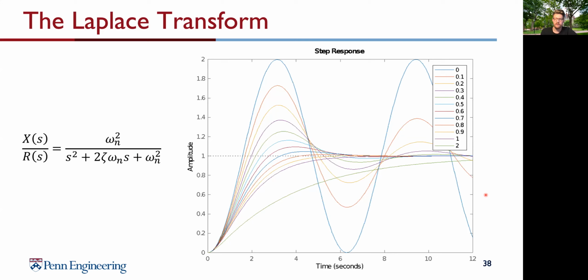The properties can be acquired by recording step and impulse responses, which we see here as the step response, or by measuring the frequency response. Step response, impulse response, frequency response, and the original differential equations contain similar information for us, because they all contain this description of the system in different form.